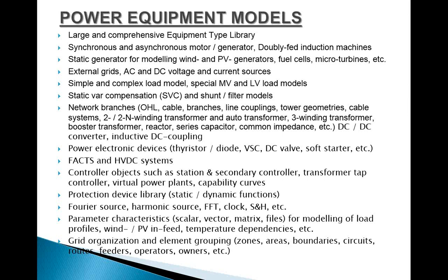Additional wind plant equipment such as controlled shunts and STATCOM facilities are there. Some stochastic wind models are also present for adequacy studies in this software. And for PV systems, we use PV cells with integrated power calculation based on solar radiation. So that kind of calculation can also be done on this software.